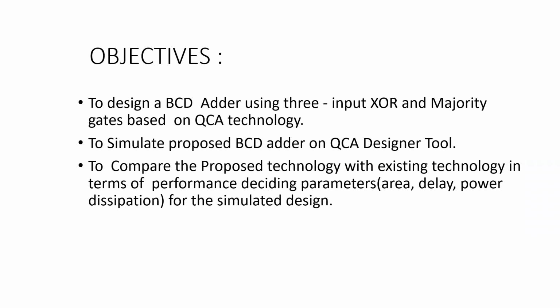Objectives: to design a BCD adder using 3-input XOR and majority gates based on QCA technology, and to simulate the proposed BCD adder on a QCA Designer tool, to compare the proposed technology with existing technology in terms of performance deciding parameters: area, delay, and power dissipation for the simulated design, where QCA technology is a new nanotechnology. A lot of emerging techniques can natively realize majority gates, although enhanced gates such as exclusive OR are implemented by several majority gates.